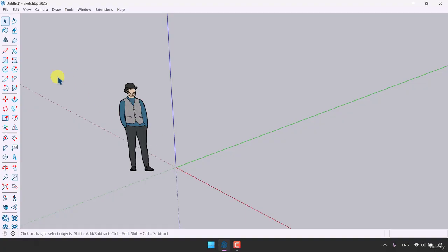So I'm going to start my 3D modeling with the Rectangle tool. I'm going to click on the rectangle, move my cursor to the origin point and start my drawing. For example, I want to draw a box with, I think maybe, 60 centimeters as the width or depth of it, and 190 centimeters for the width of it.